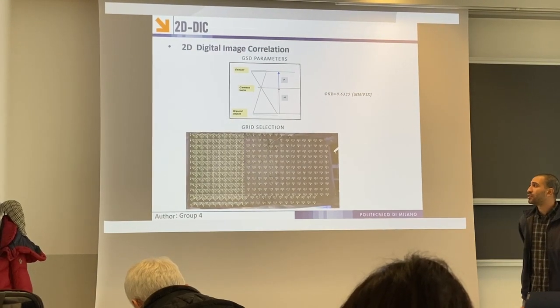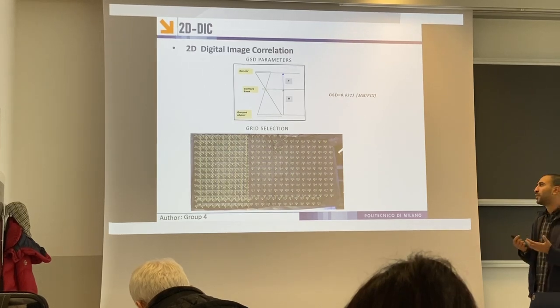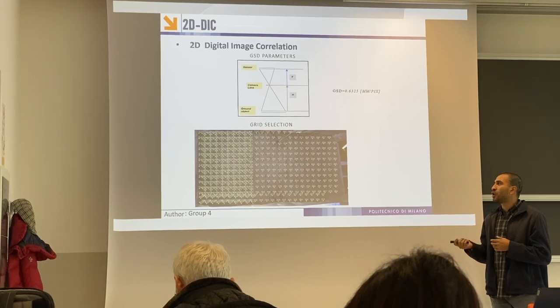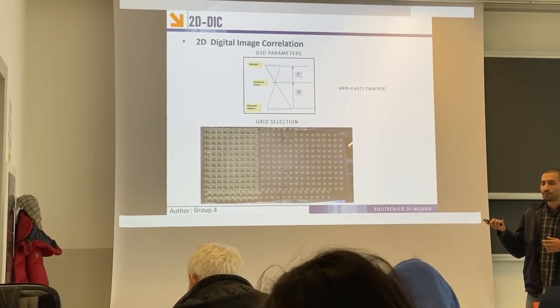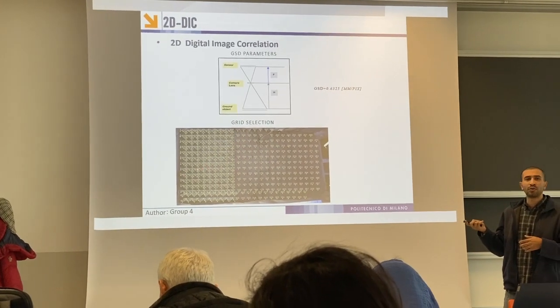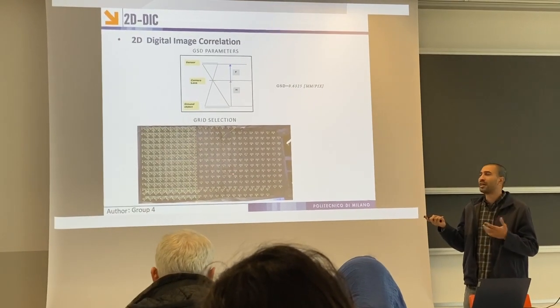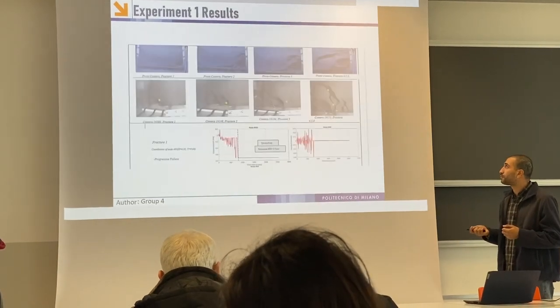Secondly, in MATLAB we have tried to decrease the computational cost, to better have a sense of the algorithm that's happening. So we have divided our mesh into two parts. The first is a very fine mesh, for the part that had a lot of cracks. And the other one is the coarse mesh, for the part of the landslide that didn't have any cracks. By this, we try to optimize the computational cost.